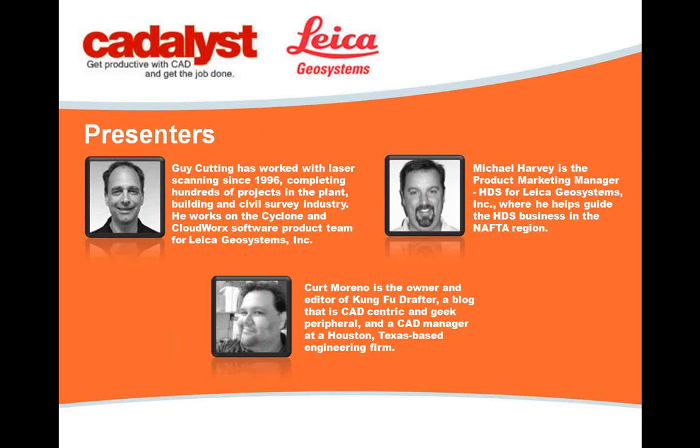Unfortunately, no. That's a frontier that I know is being worked on. I've gotten that question a gazillion times. I want to scan on top of a bridge and get the water up and get the riverbed underneath. Unfortunately, it's just the nature of laser and water that they don't work together that well, and plus the refraction of the laser through water means the location is going to be a little off.